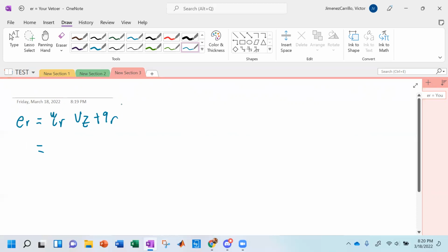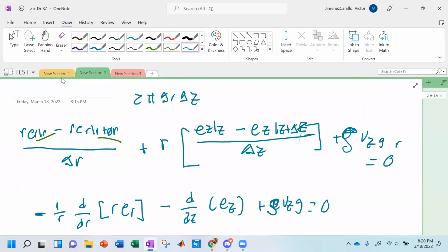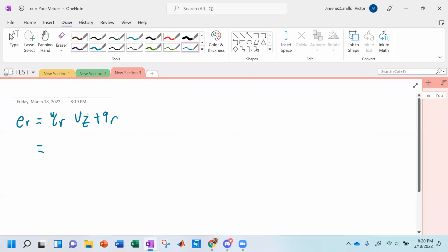Wait, can you repeat that? There is flow in this pipe, and it's coming down the pipe. Oh, yeah, so that exists. Beautiful. And the beautiful part about this is that we can replace tau the same way we've done before. Negative mu dV_Z/dR multiplied by V_Z, plus q_R.